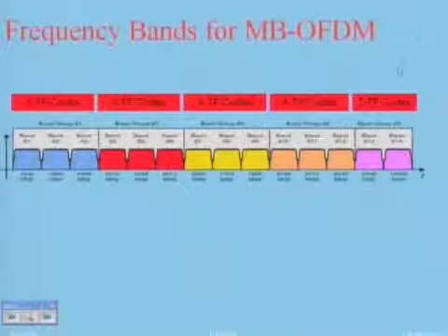So, in summary, in this second part of lecture 11, I talked about the 802.15.3 channel model for ultra-wideband communication. And briefly, I went over 3 system implementations for ultra-wideband. One was 1-band impulse radio. One was 2-band direct sequence ultra-wideband. And the other one was 14-band multiband. That's why they call it multiband OFDM techniques.